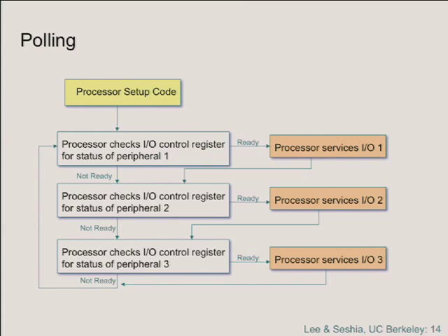Okay. When that interrupt occurs, part of your setup also specifies, it may specify, in simple hardware you might only have 1 interrupt, in which case in the simplest processor architecture, when an interrupt occurs, the processor will take the current program counter, push it on the stack, and replace the program counter value with a fixed address and start executing code at that address.